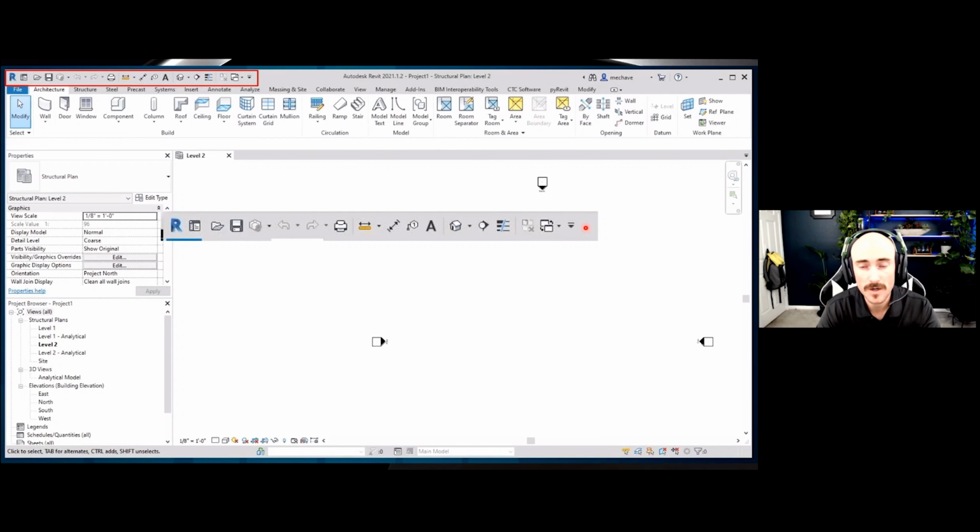By default, when we open or install Revit, we're going to see this same quick access toolbar. The reason why folks have it below is because when we're adding more to our quick access here, it'll start to fill out to the right. If it's up at the top, it'll actually stay in place and you'll have to find your new ones underneath the down arrow, which for me is very confusing. It's harder to get access to them. It's not really quick picks. That's why a lot of folks have it below. I'm fortunate enough to be an instructor, but unfortunately, I can't have things changing because I'm teaching people from the new user interface. But I would recommend docking it below if we're having more of those quick picks.